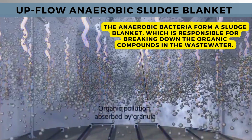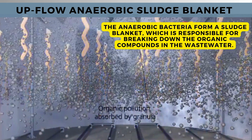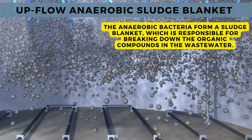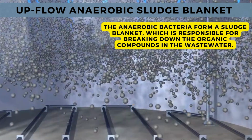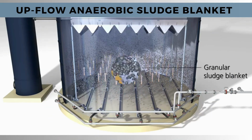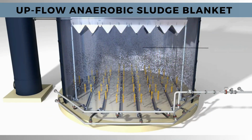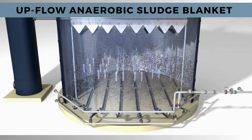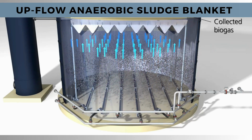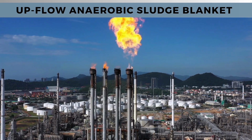In the sludge zone, the sludge settles and grows, forming the sludge blanket where the anaerobic bacteria are responsible for breaking down the organic compounds in the wastewater. In the active sludge blanket, as the wastewater flows upward, it passes through the sludge blanket. Here, the microorganisms convert the organic material into biogas and biomass. The sludge remains suspended due to the upflow of the water.